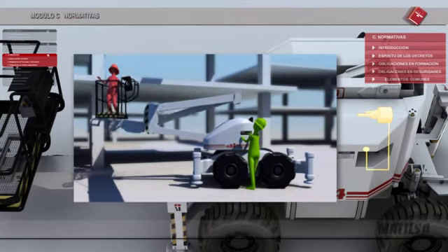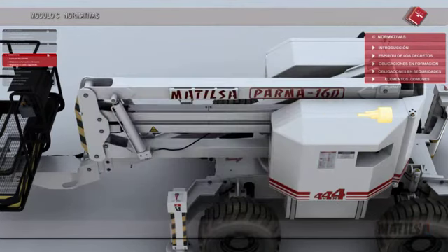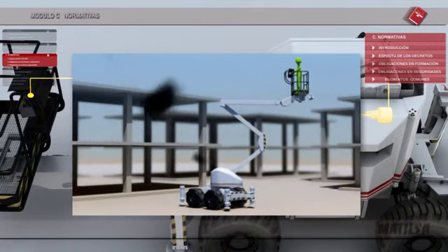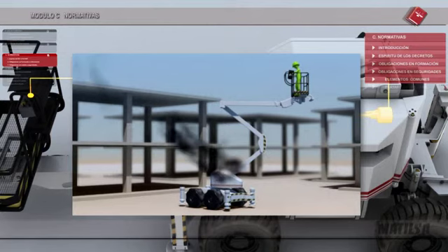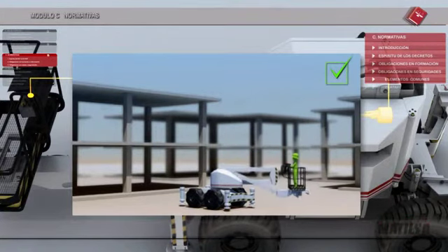Additionally, during the use of the access platforms, apart from the personnel that handle the machine, there should be personnel on site for possible emergencies. The pump may also be found on the board of controls in the basket. The lowering system may be by gravity or by the use of auxiliary pumps with 12-volt power or manually operated. Its function is always to lower the platform when a breakdown occurs or in case of power failure.